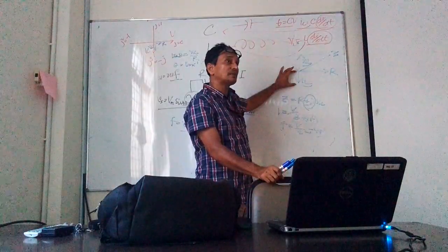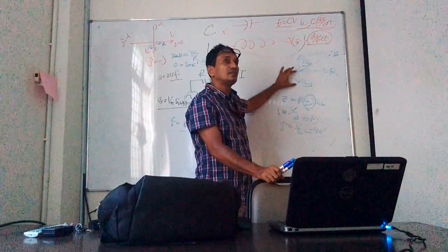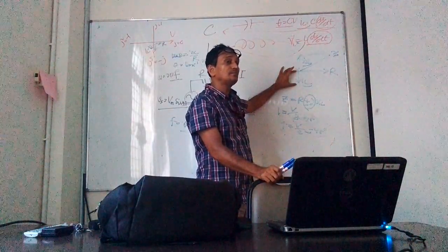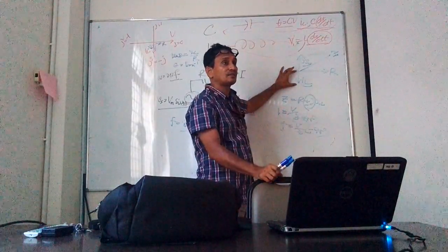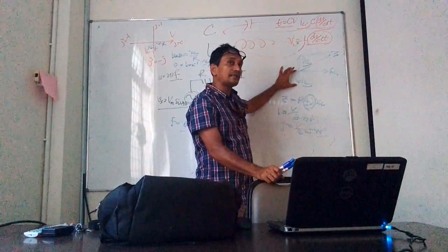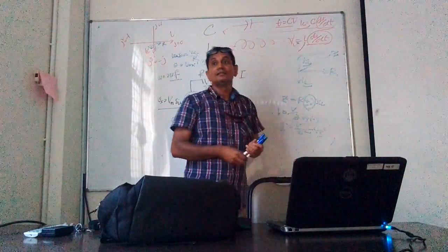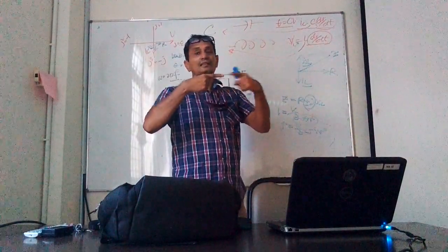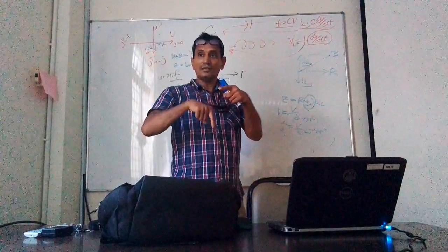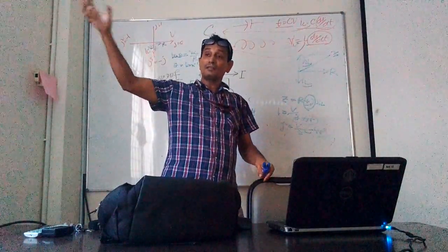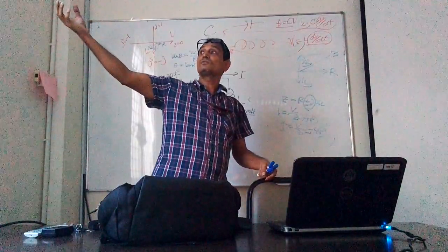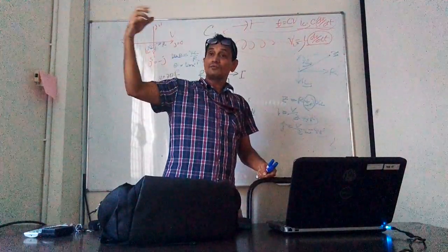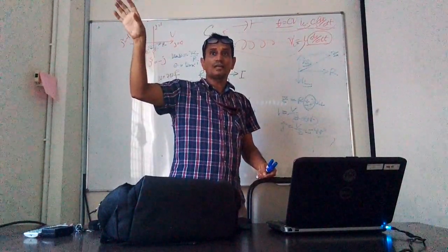And this is a major problem. Inductive current lagging is a major problem in the industry. Every industry, chemical industry, electrical industry, everywhere. What is the problem? I will discuss it. I have the video, I will transfer it to you. The problem is inductive current lagging. The current flowing through the power line always tends to make high power; current and voltage should be in the same phase. But if it is lagging, then it is not in the same magnitude, yeah? If it reduces, then the supply company, say SESB in Sabah, needs to flow much more current through their line. So much more current flow means their line drop and line power loss will be high.